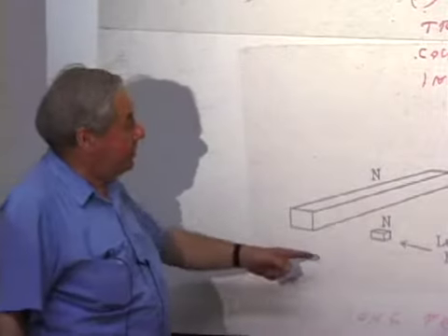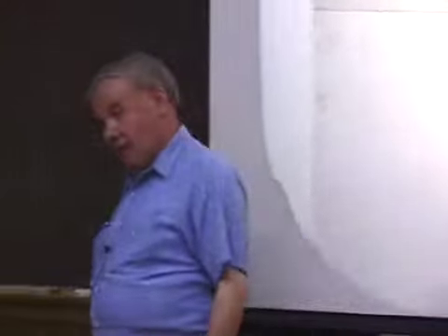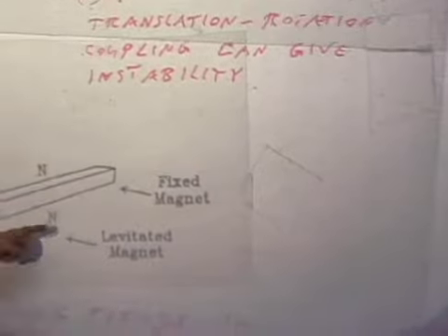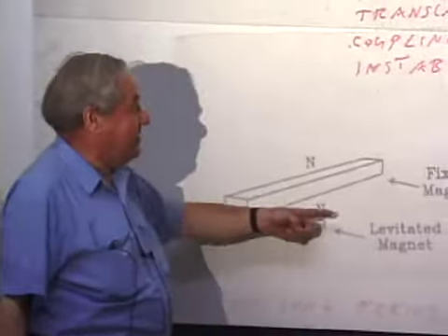But we monitor the height with a laser beam. It's a simple way: we just have a beam coming along here, and if the mass comes up, it casts a shadow, and the photodiode sees that. We put a very small coil around this, driven by that photodiode system with amplifiers and such like, so that in fact it stabilizes itself. If you get it all right, it nicely floats at a certain height below here.